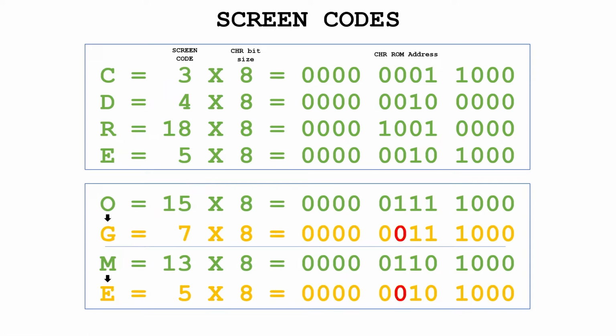And you may notice that, again, on both of these characters, you have a stuck bit, which is stuck to 0. It's a bit which is supposed to be 1, but actually 0. And if you check on the good characters, you notice that that bit happens to be 0, so that's why they displayed correctly. So again, it's the same logic that we did together with assuming that it was a data line issue, but this time looking at address lines rather than data lines for the reason I mentioned.